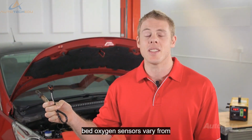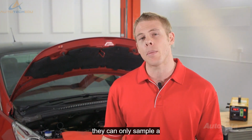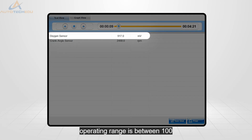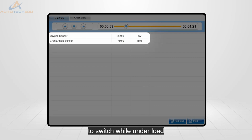Narrowband oxygen sensors vary from single to 4-wire. Like the name suggests, they can only sample a narrow air-fuel ratio. The operating range is between 100 and 900 millivolts for a correctly operating zirconia sensor, and may display as a rich to lean cycle, while a titanium sensor can display voltages between 0.5 and 4.5 volts. At idle, the sensor may be slow to switch, while under load at 3000 RPM, you will see the voltage cycle quickly.